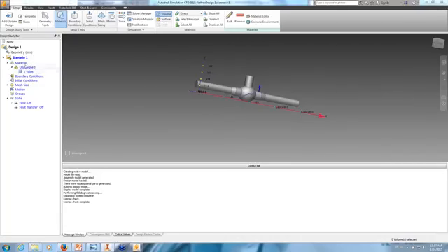You can see that it is set here to unassigned. I can select the part, which is one part only here, and click on edit. That's one way of doing it, or I can click on the edit button up here. Either way, when the part turns red, it indicates that it is selected. If you have selected more than one part, one way to make sure that you have the correct number of parts is if you look at the lower right corner of your screen, it says one volume selected.